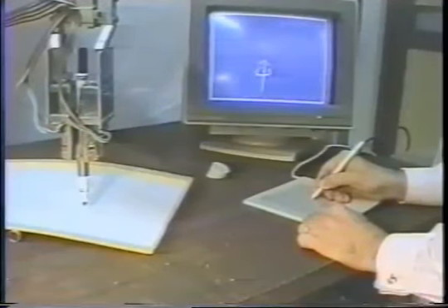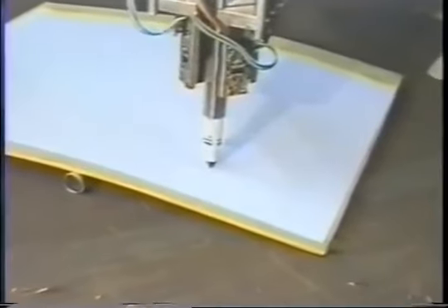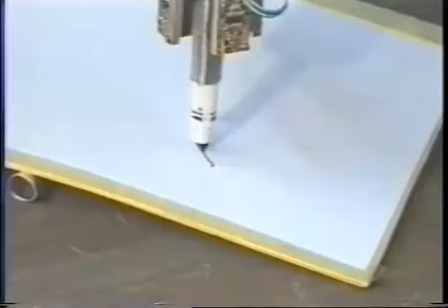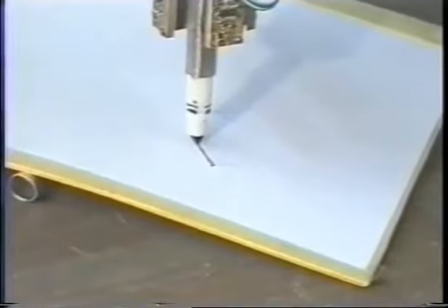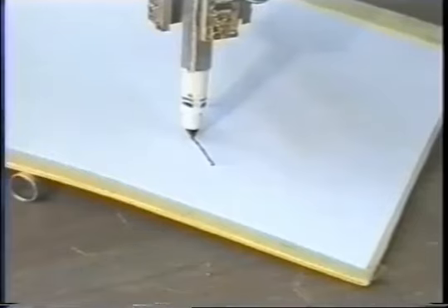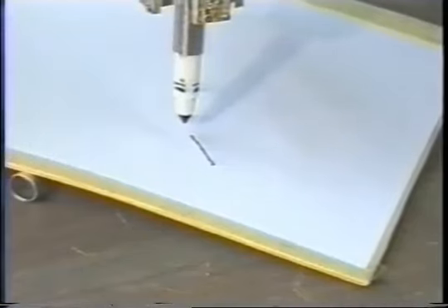Measuring intensity and direction of the reaction forces enables the robot to keep the pressure on the pen tip constant, as demonstrated in the next experiment. The robot draws a handwritten figure on a curved, unknown, and arbitrarily inclined surface.